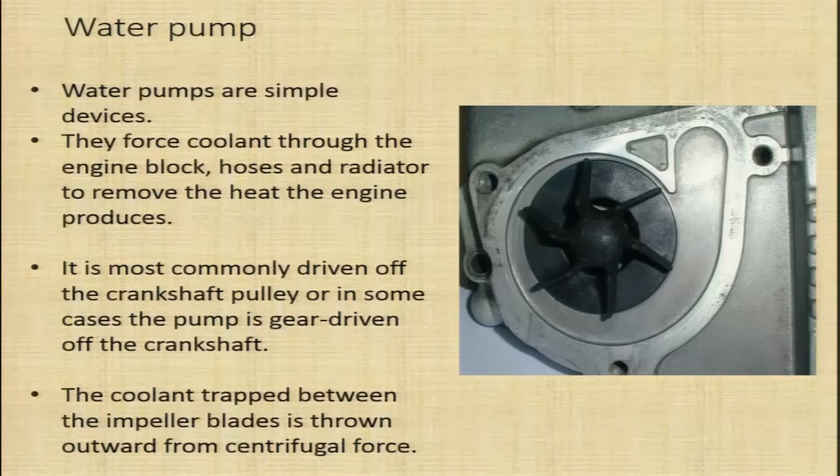So, let us see what a water pump is. It is a simple device. It forces coolant through the engine block or the radiator hoses to remove the heat the engine produces. It is most commonly driven off the crankshaft pulley, or in some cases the pump is gear driven off the crankshaft, and in one of the examples we have seen that the water pump was driven by the camshaft.